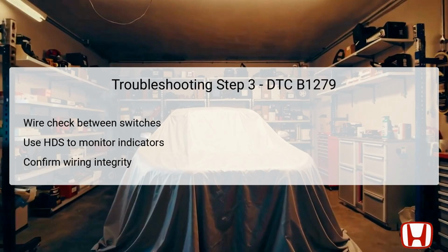Begin by turning the vehicle system to the off or lock mode and disconnect the combination light switch 12P connector to ensure safety and avoid accidental shorting during testing. Connect terminals A and B using a jumper wire. Terminal A is for the body control module connector A, 66P, number 25, and terminal B is for body ground.